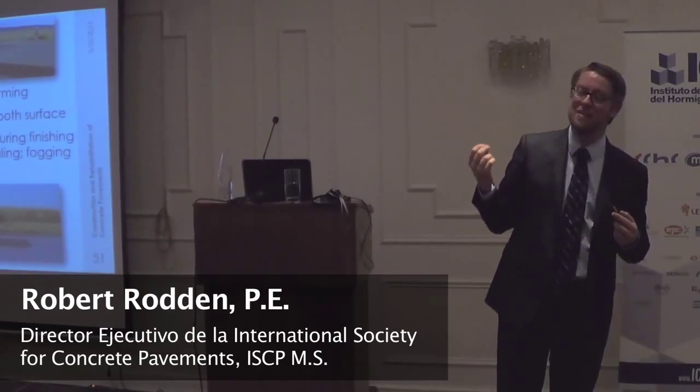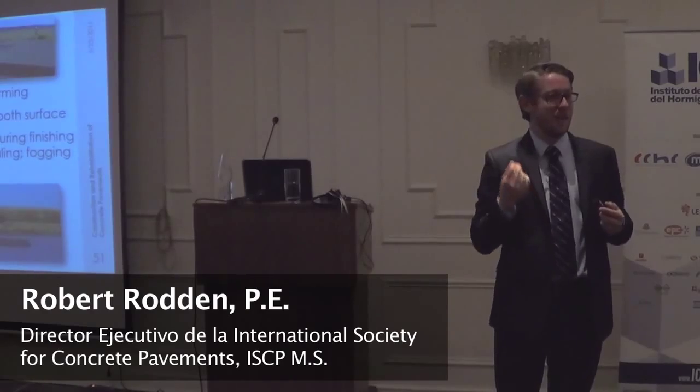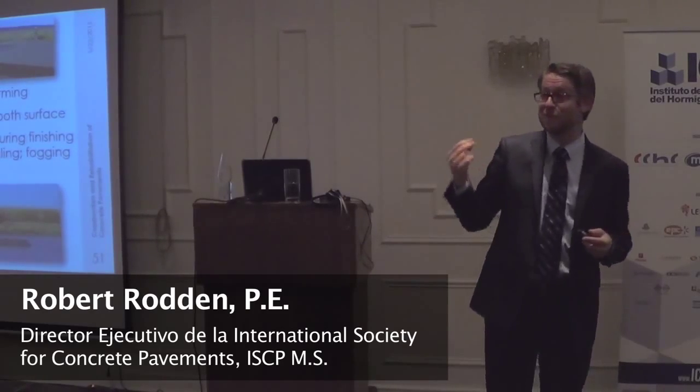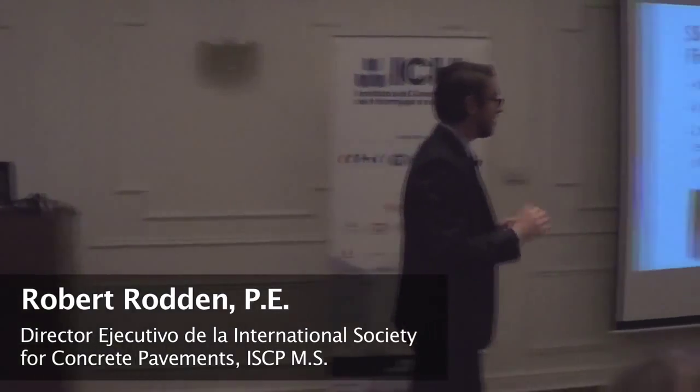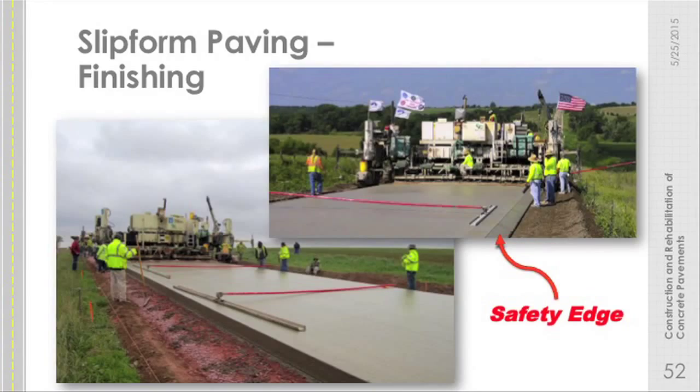That's the point that is most critical. If you're going to have freeze-thaw damage, it's going to happen at the surface, not in the middle of the slab. So you don't want to do that. No adding of water at the surface. Some more photos of finishing, so we can see those. If you're paving several lanes wide, the handles will become very, very long on those straight edges.